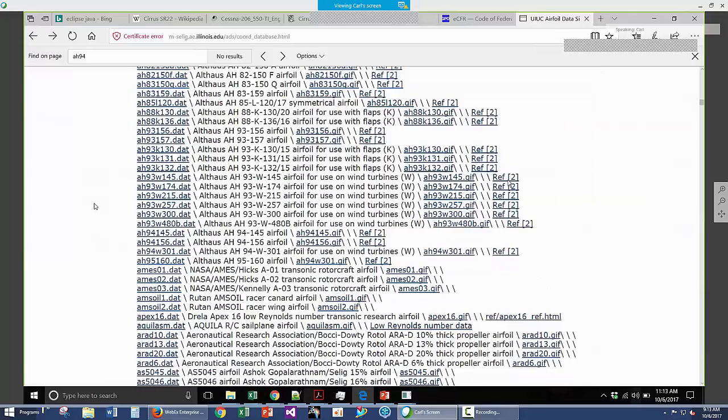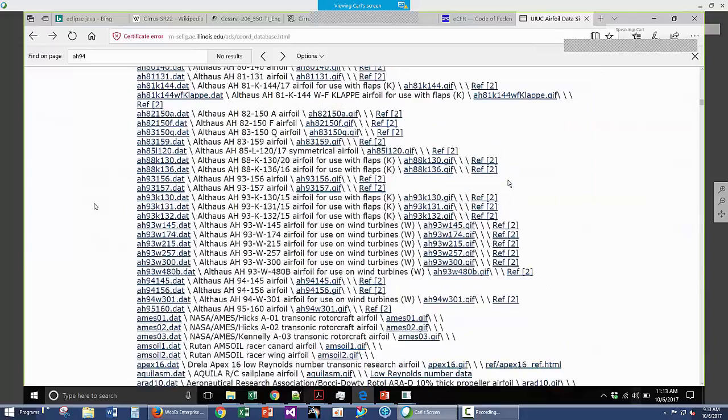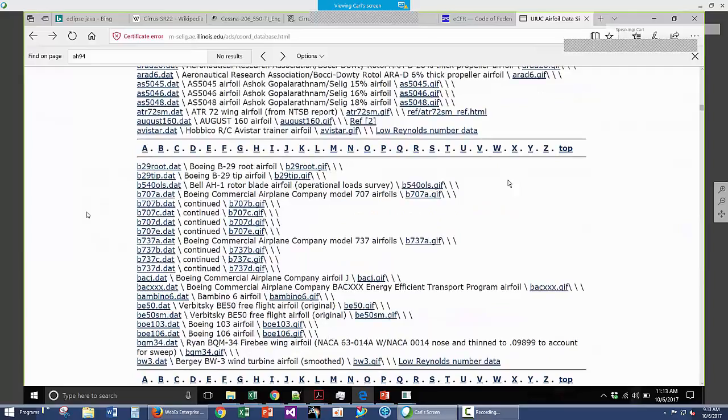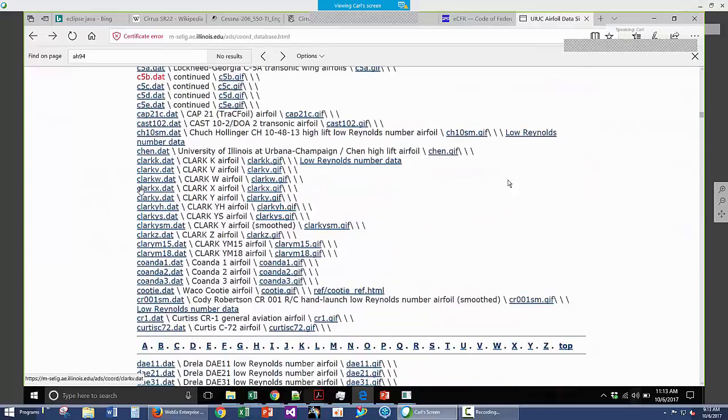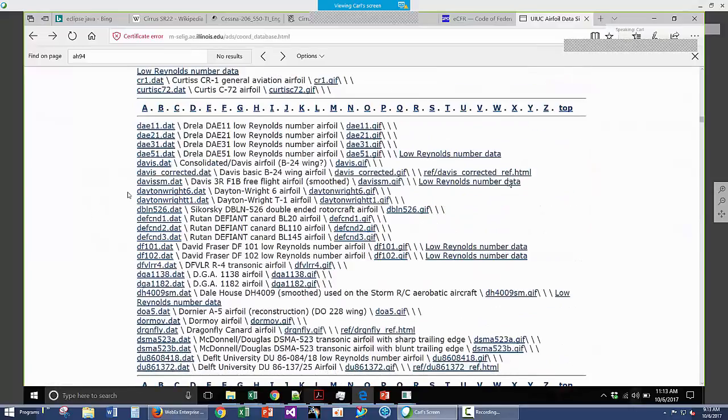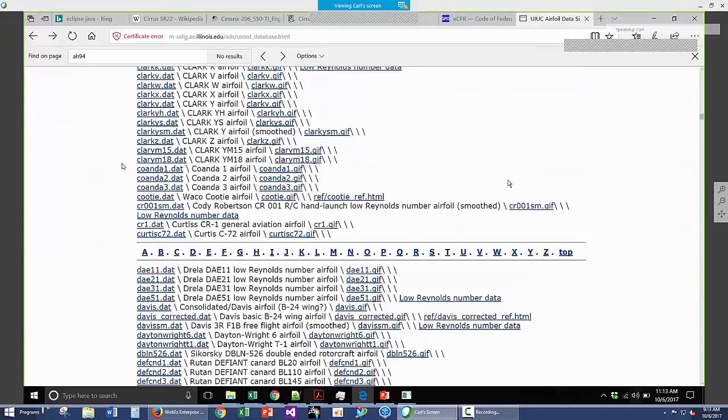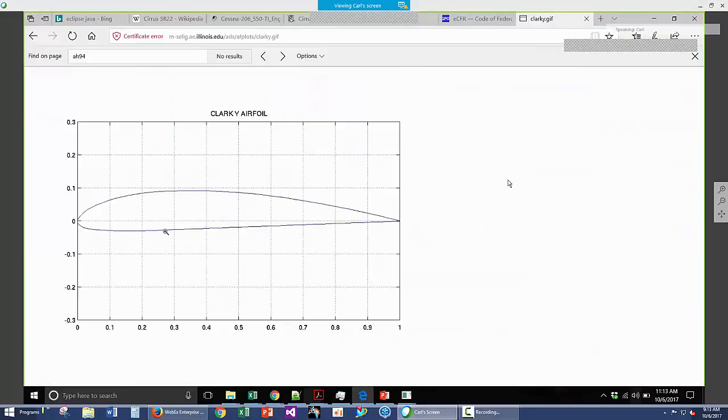You've got to be careful using airfoils that are too thin, because those can become impossible to build, and it also takes away all of your thickness, right? Something that's used very commonly for model aircraft is a Clark Y, and that's because it has a nearly flat bottom.